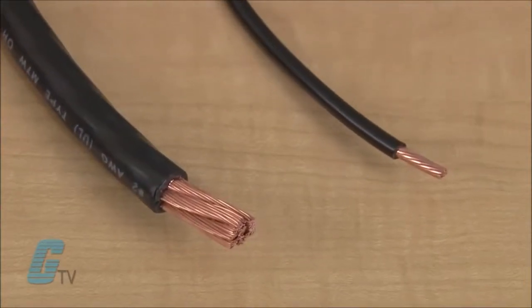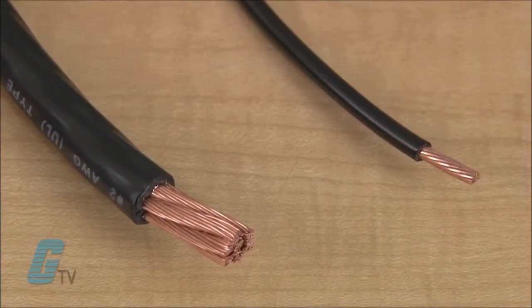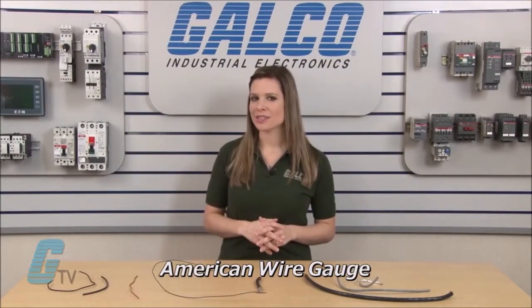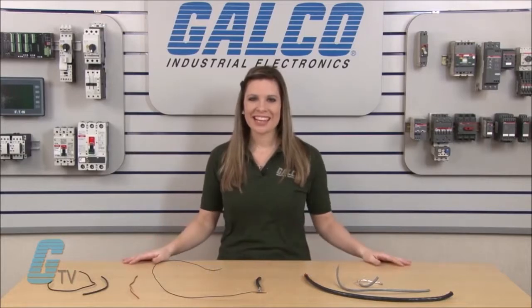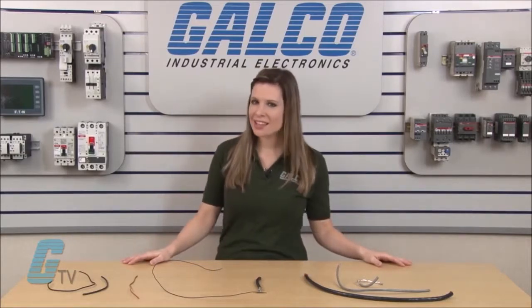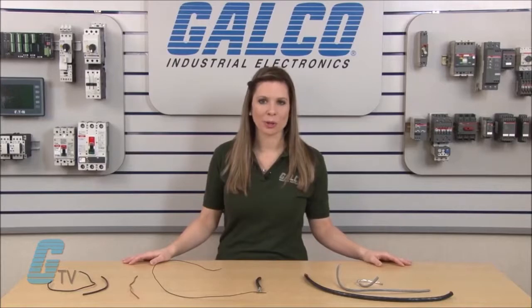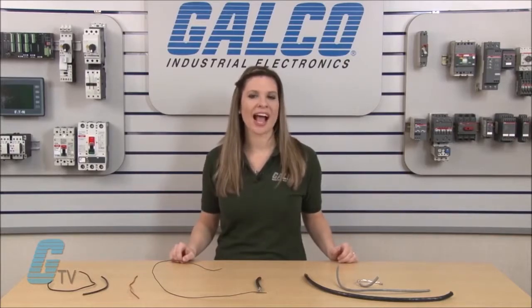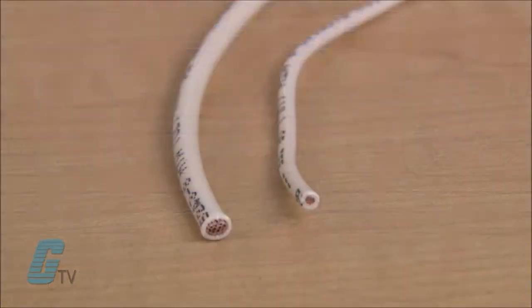Sizes of wires and cables can vary between regions, with the three most popular being the AWG, Imperial, or Metric. In the United States, the AWG, known as the American Wire Gauge System, is the standard. The AWG increases in size as the gauge size gets smaller. For every 6 gauges in difference, the lower gauge wire is about twice the size and diameter of the higher gauge wire. For example, a 10 gauge wire is twice the diameter of a 16 gauge wire.